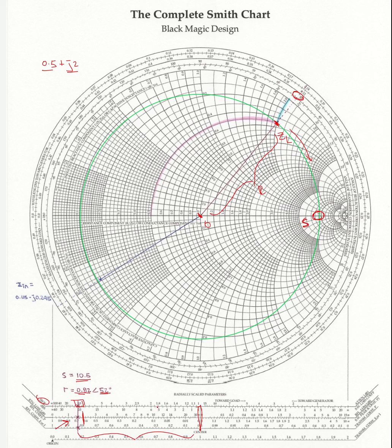In terms of how to find Zin at the specified distance, all we need to do again is find the radius, follow this all the way up, and then add the 0.275 wavelength that we were given. In doing so we will follow this entire circle around and end up at this particular position. The distance, of course, is going to be the same as the radius between ZL and 0, and so this spot right here is our Zin value, which I've also written here.